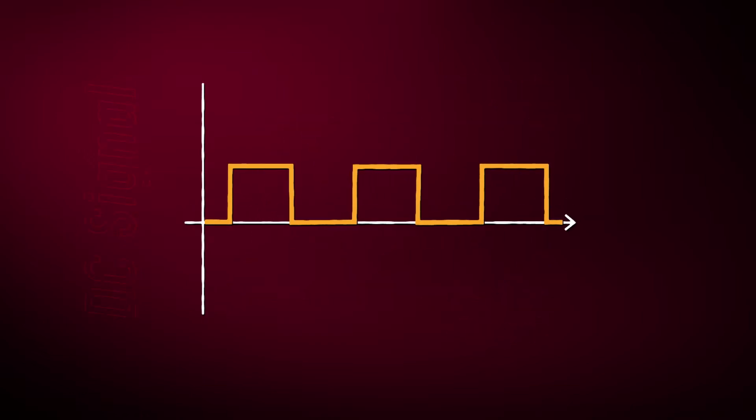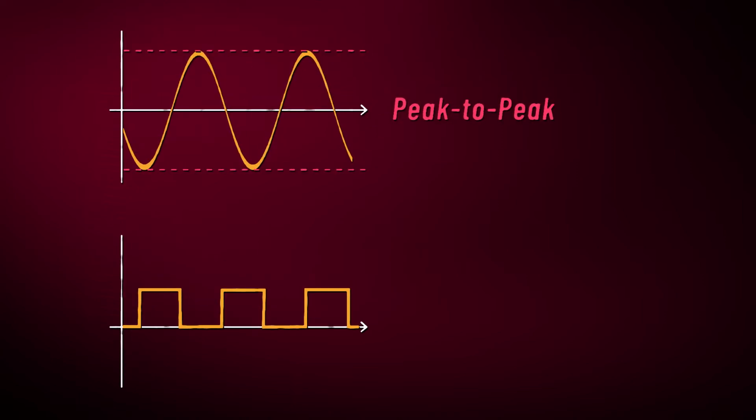If we look at this DC signal, well, there is no alternating portion here or here. It may look like these valleys are alternating portions, but they're not. They simply return to 0. They never hit a negative signal. A DC signal will never have a peak-to-peak voltage, known as VPP for short. DC signals will only ever have a 0 to peak signal.